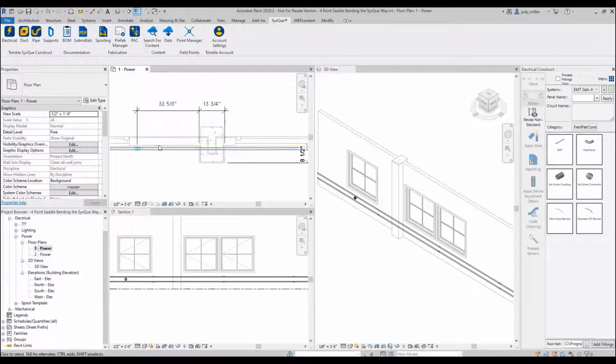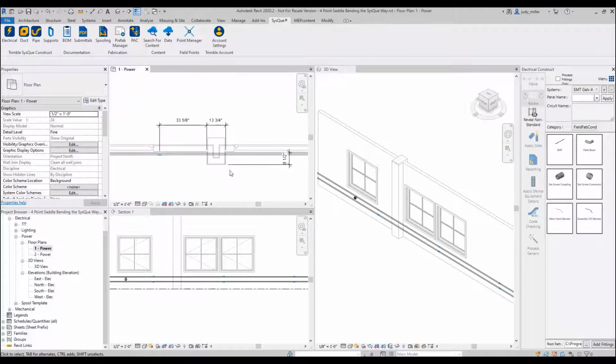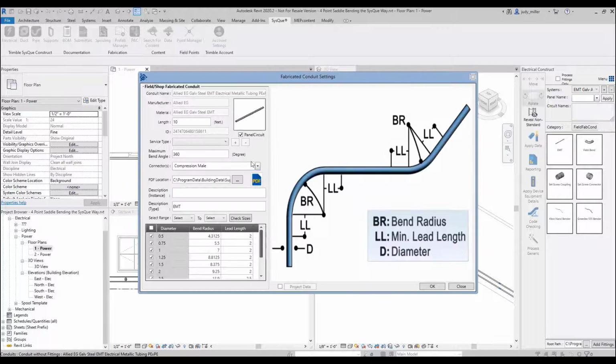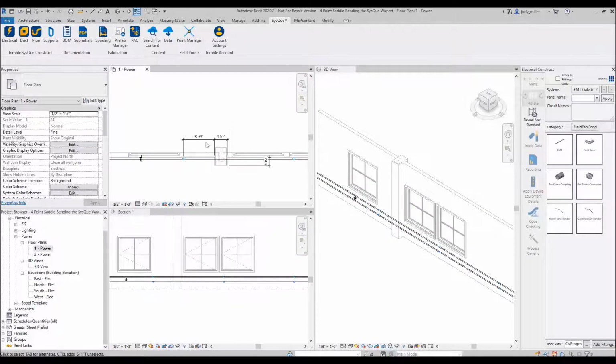We approached the column, I ran through the column. Of course, we can't do that with the conduit, so we're going to have to put a 4-point saddle in there. I dimensioned, so I let SysQue place my couplings for me. And again, as a review from earlier, we've set this up to place couplings every 10 feet. So that's where that came into play.